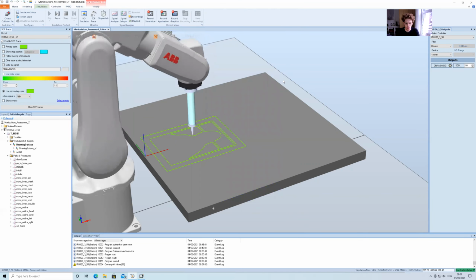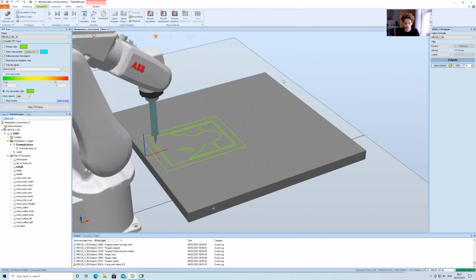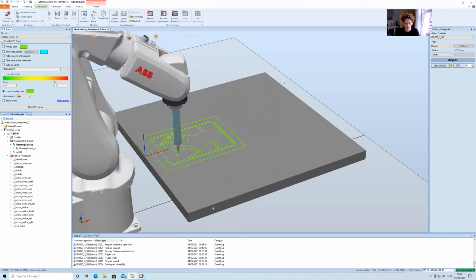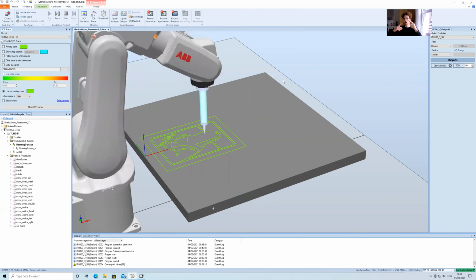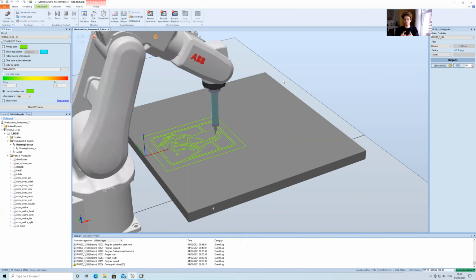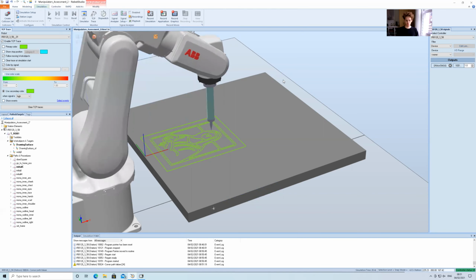And the corners, without the wait operation to ensure that the signals have been set, you often find that the first and last point do not close properly, so they're left a bit empty. So whilst waiting, we're ensuring that we have successfully closed the path. Effectively, in this simulation here, the TCP has closed the path, we've turned off the draw signal, and then we've moved away so that we don't show the